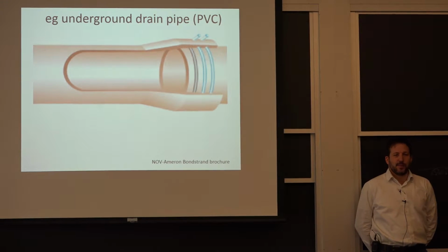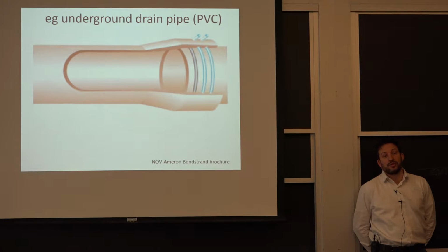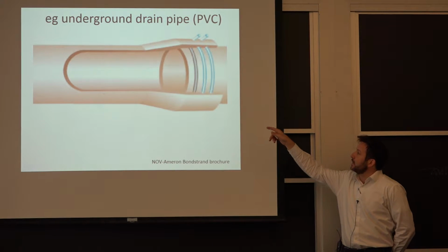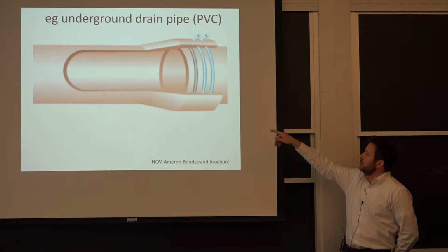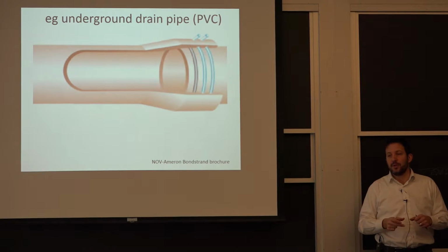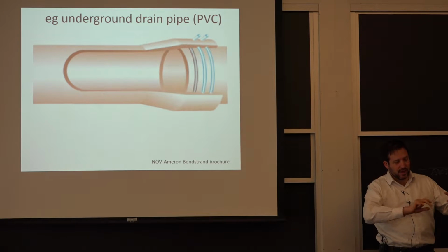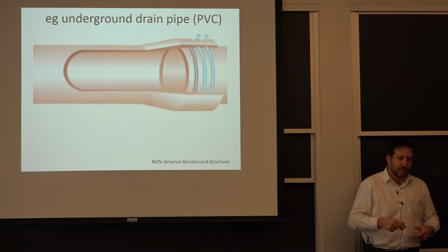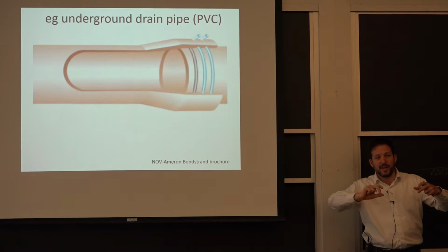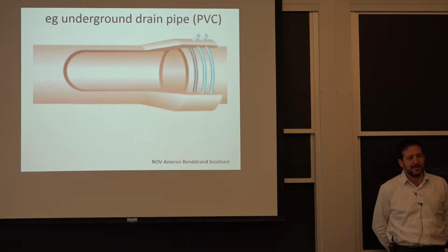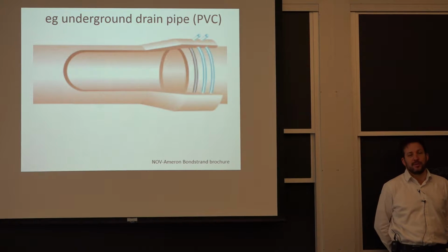So there are pluses and minuses with respect to general use. One of the advantages, and that's what I'm showing here, is there's a much easier way to make these products without having to put threads that are long to do. When you try to put a steel plumbing system together for fire sprinkler, you have to thread each connection, and you have to do it in a special sequence to be able to build your system. Whereas here, if you're just trying to insert things together, they can rotate after, and you're still holding the pressure. It's not a problem. So a seal system like this one is just a lot more flexible for use.